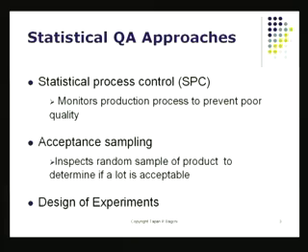In the old days, the only way to control quality was by inspection, and the statistical procedure which we covered in the earlier sessions, one of those was called acceptance sampling. You basically collect a few samples from a handful of items, and based on the quality of these samples, you decide whether to accept the lot or to reject the lot. That particular procedure was called acceptance sampling. That was one way to apply statistical methods in quality assurance. And this online control business comes under statistical process control or SPC.